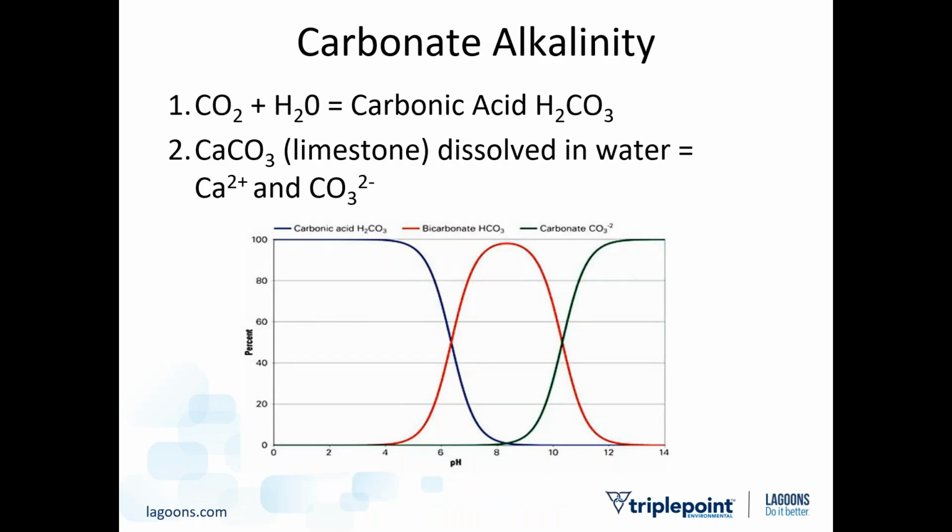So I've mentioned a few times carbonates, which come from limestone, as an important species in pH, and they are the most important species for alkalinity. Carbonate alkalinity is usually pretty equivalent to total alkalinity in anything but the weirdest of industrial laboratory type water situations. And bicarbonate carbonic acid is a pretty fascinating molecule.